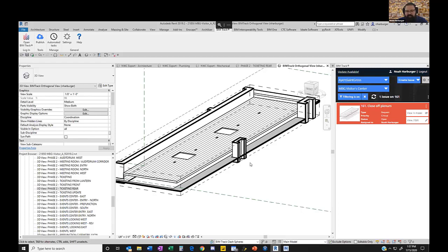there's plenty to be said for what gets modeled and how it gets modeled, so that it becomes clear on the drawings versus how it's going to be installed. We all know that pipes get modeled a lot further apart from each other than they need to get installed, so that they can be legible in the drawing sets. So if those sorts of clashes show up and we see there's plenty of space right next to this, that's fine. We just hit accept and move on. This is really just to focus on those issues that really are issues.